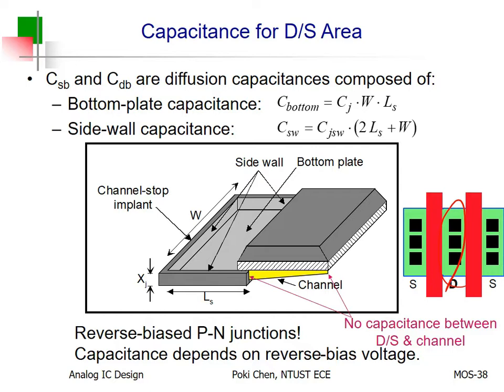The short side wall is shared with you and me. And how about the bottom plate? Only 1 bottom plate, also shared with you and me. Bingo. So in the middle region, on average, each MOSFET only needs to take 1 short wall and 50% of the bottom plate for parasitic capacitance.